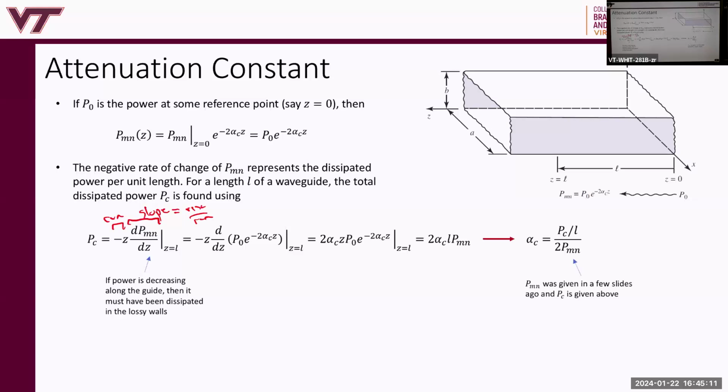Current on the walls inside it. Yeah, so what we've done here is we've modeled the wall with a resistive sheet impedance, and we're assuming that that's impenetrable. So all the loss is happening right at the interface due to the way we've modeled the waveguide walls, which is common. If you were to do a simulation of a waveguide in HFSS, for example, you would do the same thing.